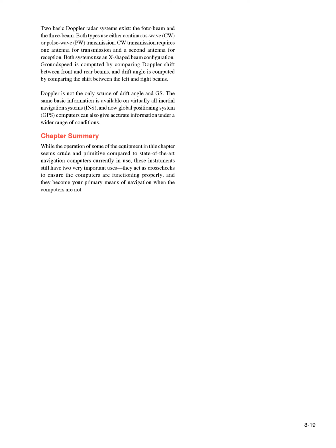Doppler is not the only source of drift angle and GS. The same basic information is available on virtually all inertial navigation systems, INS, and now Global Positioning System, GPS. Computers can also give accurate information under a wider range of conditions.